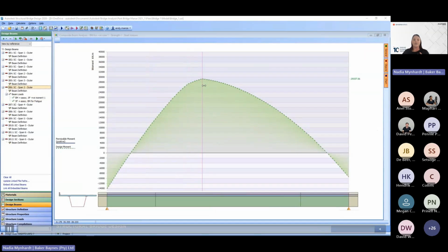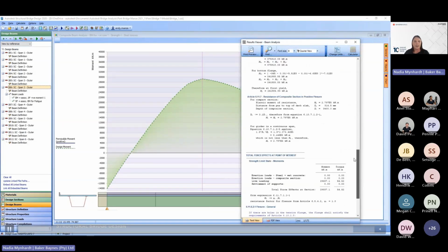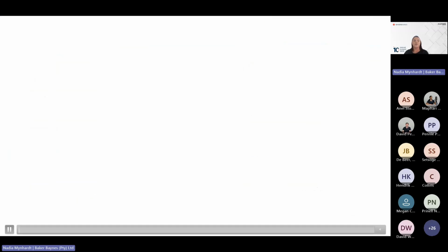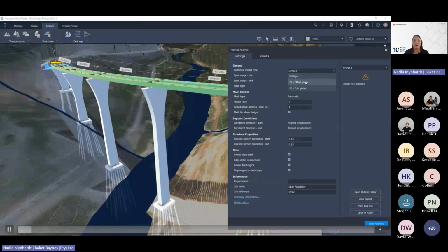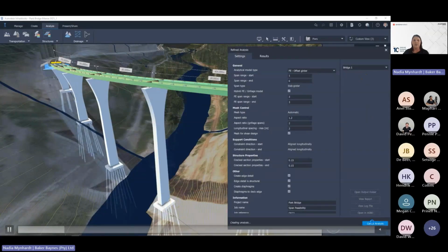And then obviously, once you have those results, you can look at them visually or numerically. You can generate a report. And once you have that report, you can now start looking at the actual design of your girders, maybe they need different sizes, or your piers, for instance, etc. So as you can see, it's fairly easy to use your Infraworks model in the Structural Bridge Design tool.